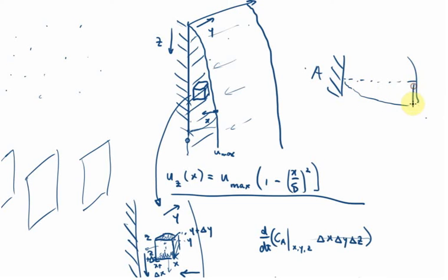So it's going to be fast here, right? U max, you are quite fast near the surface of the film, and then it starts dropping due to viscous drag, because on the other side of the film, it's not really flowing, right? No slip at the wall. So due to viscous drag between a definitely flowing part and a not flowing part, there are these in-between values. Viscous drag causes this value to change continuously. So we have a velocity profile like this, and according to the information given in the problem, this is not